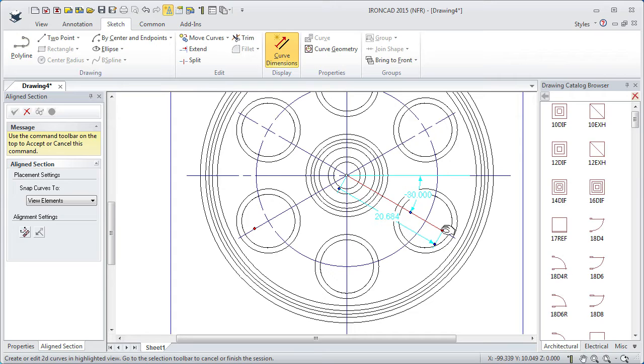Then I want to drag this line along the line of the circle hole pattern. Well, if you grab the end point of the line and you come out here, you cannot snap to anything. It's impossible because there is nothing to snap to. So I will go back and snap to that line and will grab the end point of this dimension. When I drag this node, you will drag along the line of the circle hole pattern. I will select this line. I will do the same here.